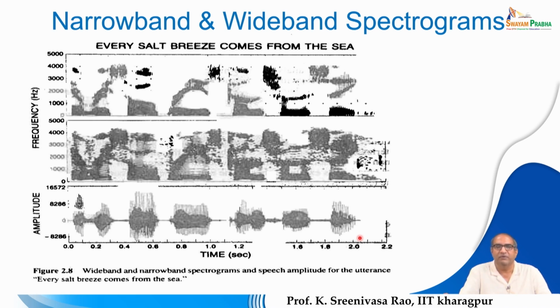That way we divide the speech signal into multiple frames. For every frame we compute the spectrum, that is the frequency components, and for every frequency, the strength or energy it possesses is also represented. The spectrogram is stacking the spectra of the consecutive frames of this speech signal.